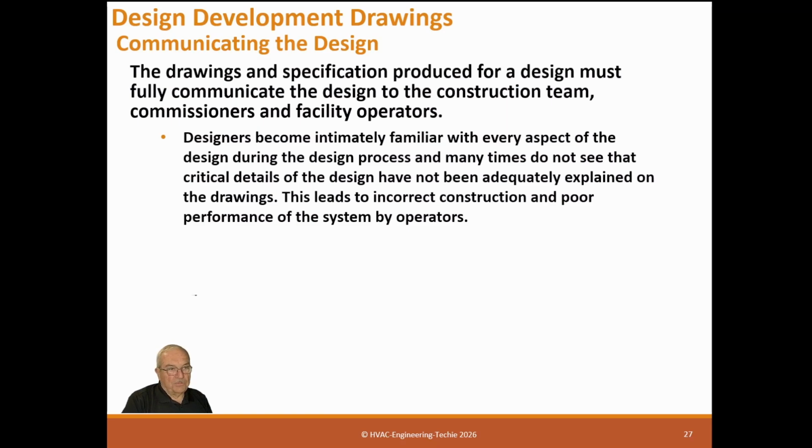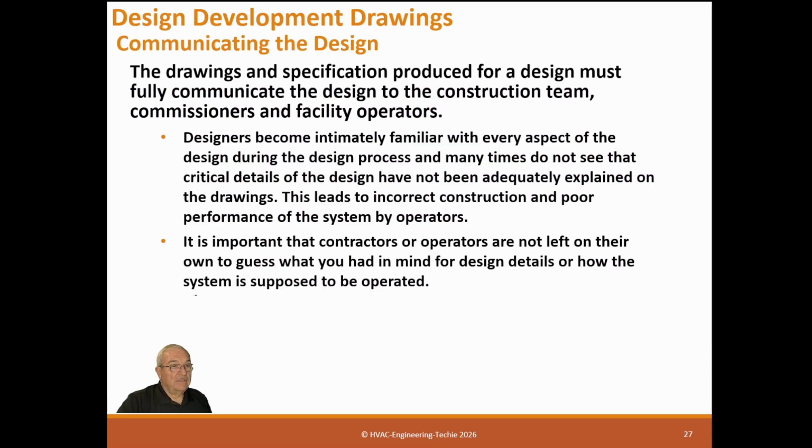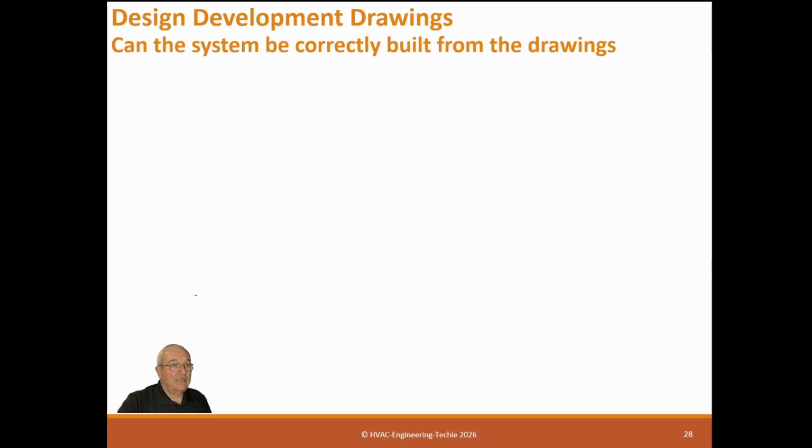It sounds strange, but you know every little detail about this design, and when you lay it out on the drawings, you don't realize that you have some assumptions that you know, because you know it, but the other people won't know it. So sometimes we have to step back and look at the drawings to see if they have enough data. It is important that contractors or operators are not left on their own to guess what you had in mind for design details or for how the system is supposed to be operated. It needs to be crystal clear, and it only takes a little note to do that.